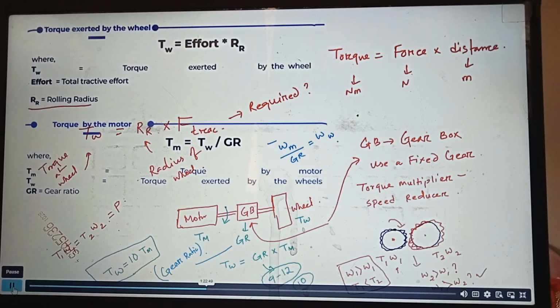That is also a bit troublesome, because high current means higher cross section of the copper winding, so even your motor size goes up. So generally, to achieve higher torque, we go with typically a 1:1 kind of gear ratio. That is easier to achieve, right? On the other side, getting a higher speed from the motor, electrical side there is not much problem, because speed is proportional to the voltage. For higher voltage systems, generally we need higher insulation, and that can be managed up to a certain extent. So that's not a problem typically.